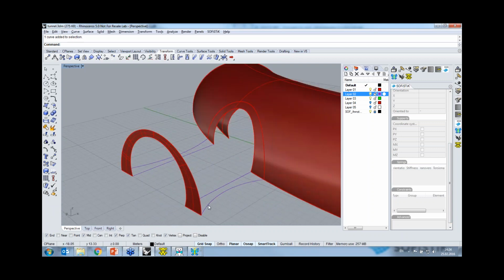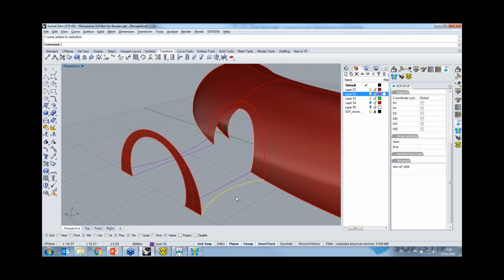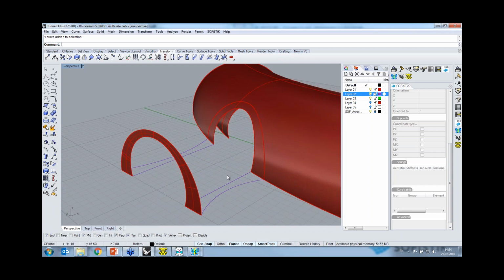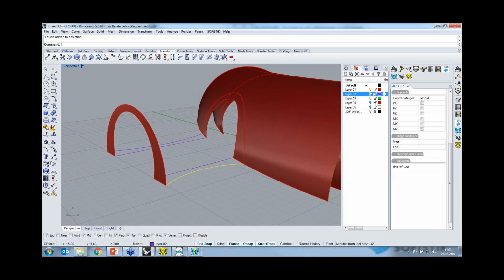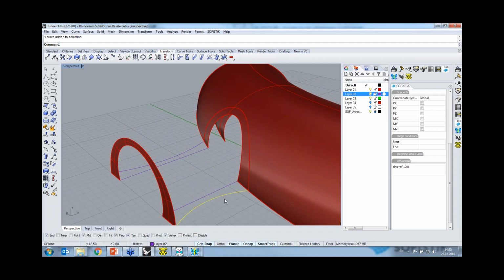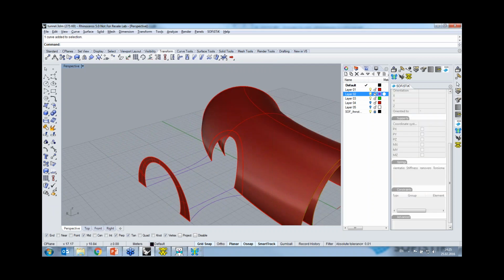Now, in this case, we can see that the guiding curves serve for three purposes. One purpose is that it helps the algorithm to make a one-to-one node correspondence between the coupled structural areas. A second purpose of these guiding curves is to define the number of subdivisions, but in this case there's also this curvature on these structural areas, on the structural lines, that will influence the geometry of the final structure.